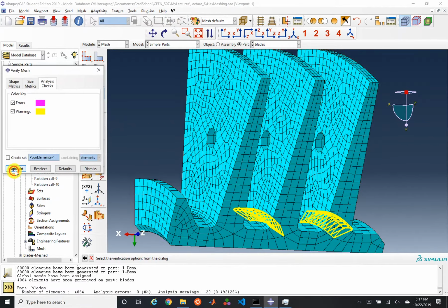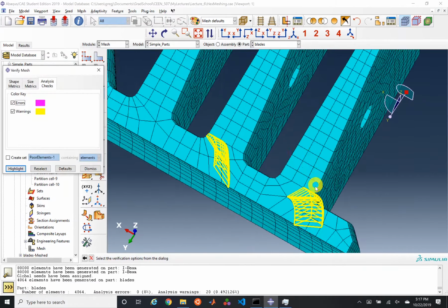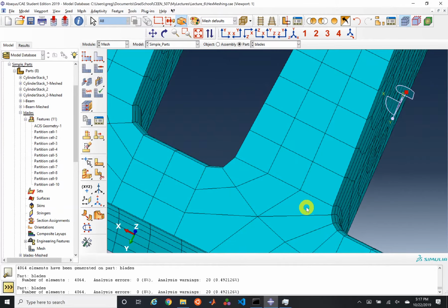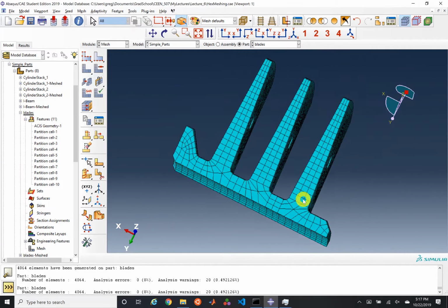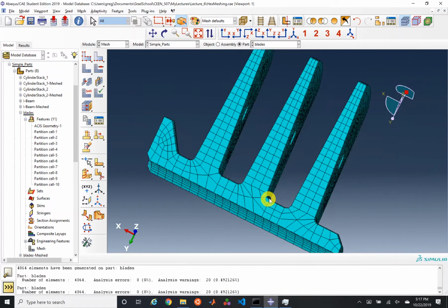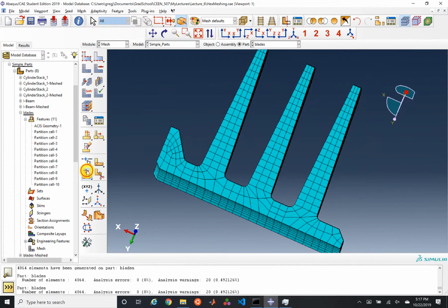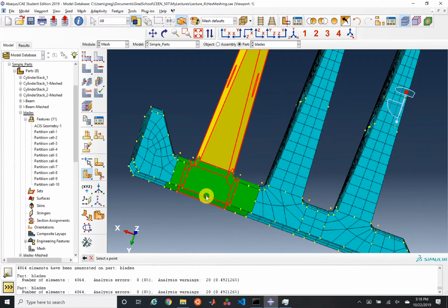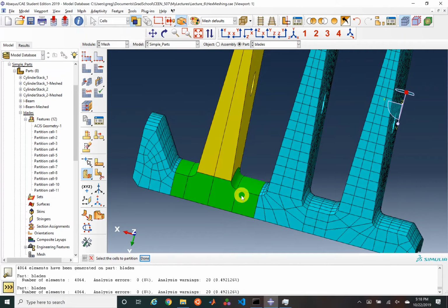Let's go ahead and just take a look. Yeah, okay, we can see there's this string of hexes here. Those hexes look pretty gnarly. So here's something I can do. We see maybe there's some asymmetries here, and this kind of screams out that what I could do is partition this geometry with a plane with this normal here. Cut them in half.